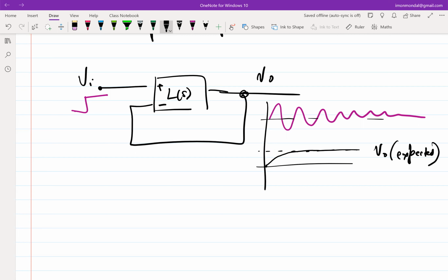If I have to reduce the steady state error, I have to increase the gain. We have explored many ways of increasing gain, cascode and all. Let's say that is also not enough. Now we want to put two stages together to increase the gain. Then if you're not careful, you will end up with this.